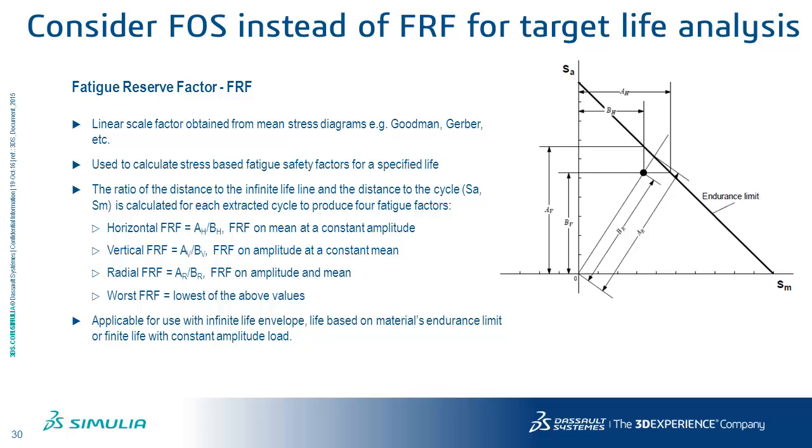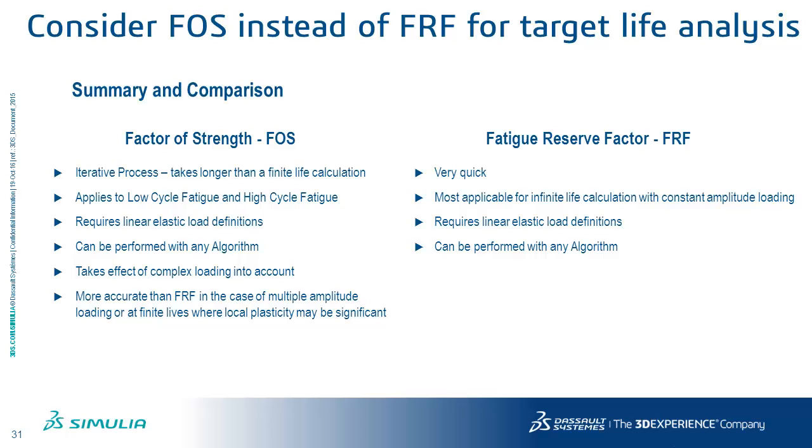If we compare those 2 methods, FOS takes a little bit more time than the FRF because it's an iterative process, but because the FOS calculation is more accurate than the FRF, you can apply it to both low cycle fatigue and high cycle fatigue.